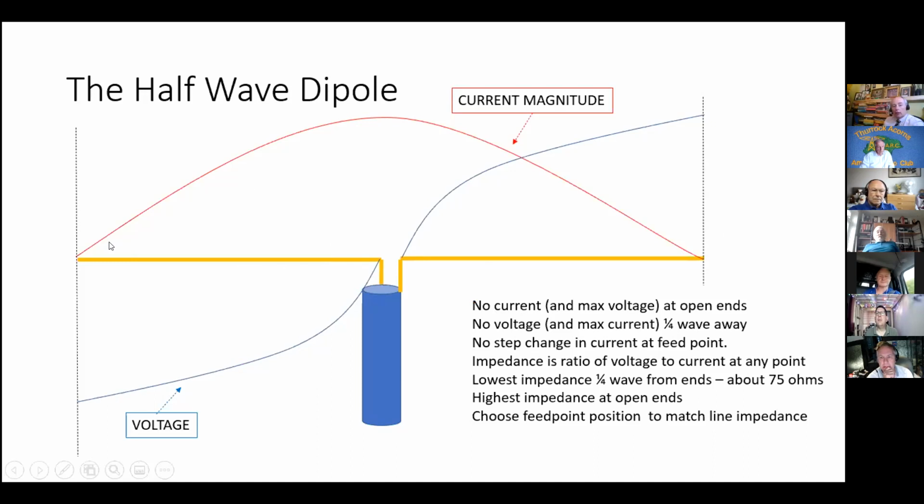And when you analyze antennas, certainly the way I was always taught to do it, is start with the ends because you know you have zero current, and then work back quarter waves to where you have a current maximum and a voltage minimum, and you plot the current and voltage distribution, and then you can analyze the antenna from there.